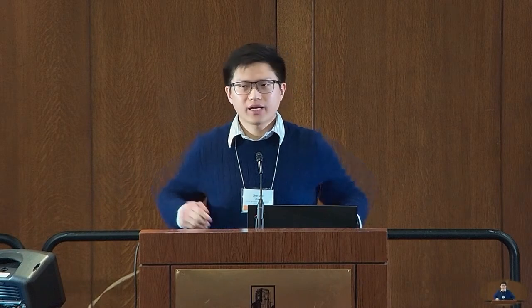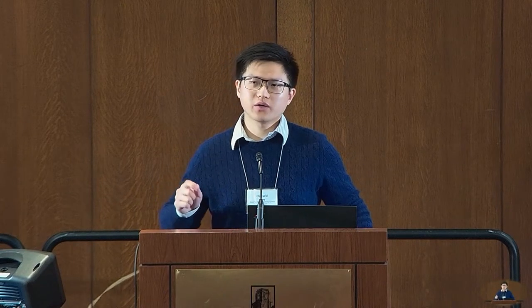Hi, Che-Wei. Thank you very much for the presentation. This is Slavko from ABB. Is the method that you proposed applicable for both TO247 with the 3-lead and 4-lead devices? Unfortunately, I haven't started analyzing the 3-pin devices, but I think the mechanism should be very similar. During the switching junction, it all depends on the degree of the charging gate current. So if our solutions can always balance this gate current, then it should be able to apply to the 3-pin devices.